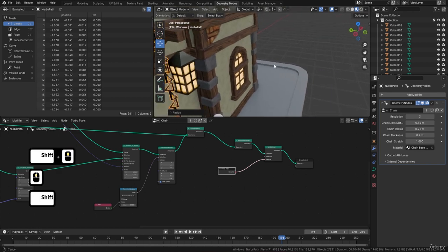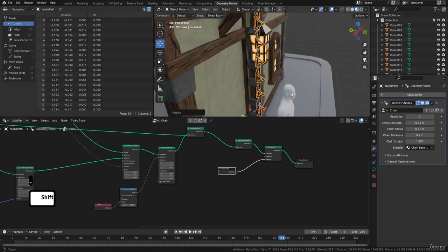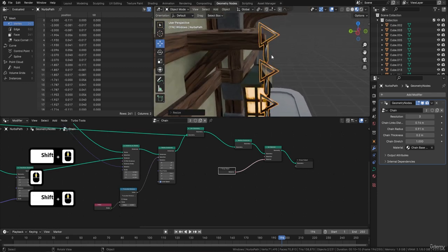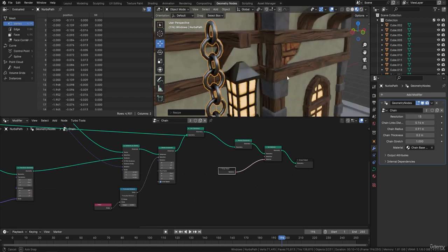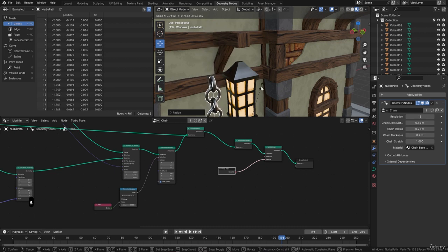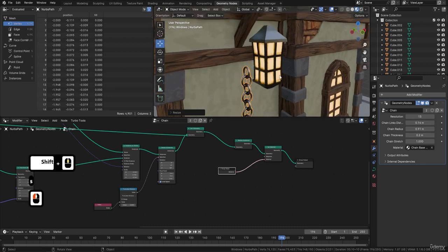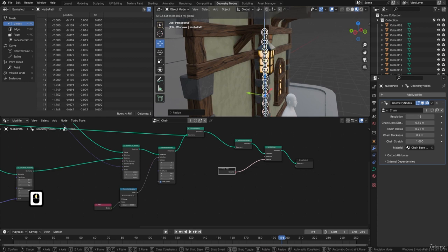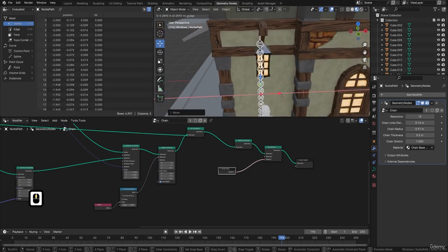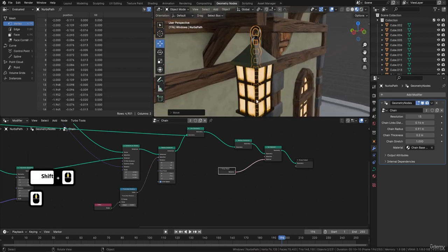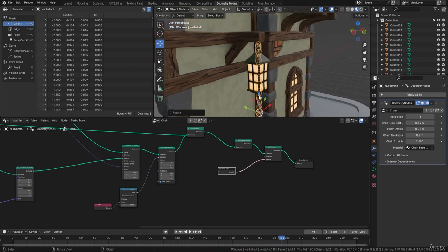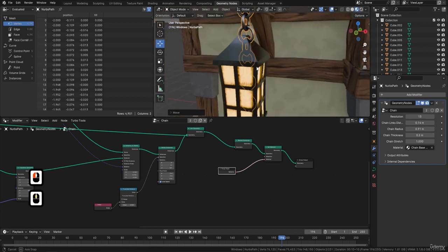And then what I'm going to do now, first of all, is I'm going to increase the resolution, because we don't want some triangles like this. So let's increase that resolution to something like there. Let's probably increase the chain thickness. I'm still going to make it a little bit smaller. I still feel like it's a little bit too big. And now once we've actually increased the size, decrease the size of this, then I can actually put it in place, spin it round, so RZ90, and then actually look at where I'm actually going to put it, and things like that.